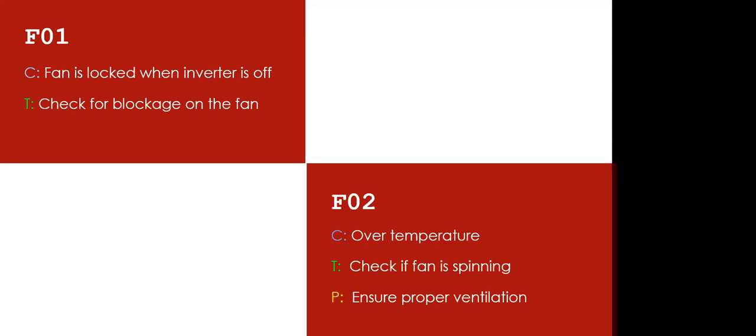So if that happens, the thermostat will sense the heat and signal the inverter that the temperature is getting too high. If the inverter keeps working in that state, it may cause damage to the main board. It may heat up the coil and burn it. So all those observations, we need to keep in mind.